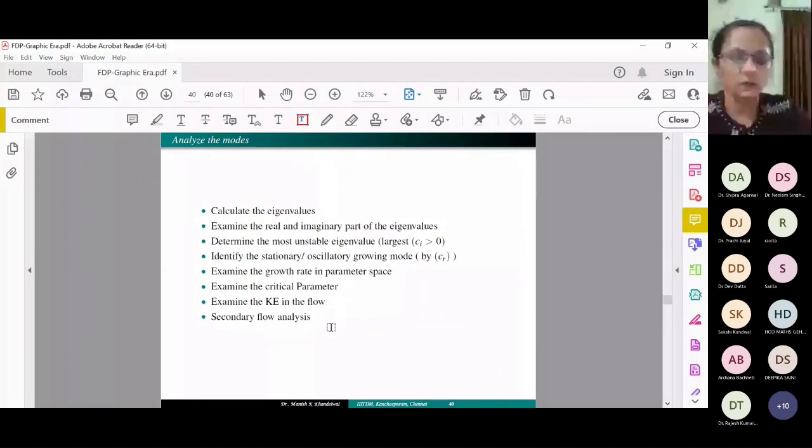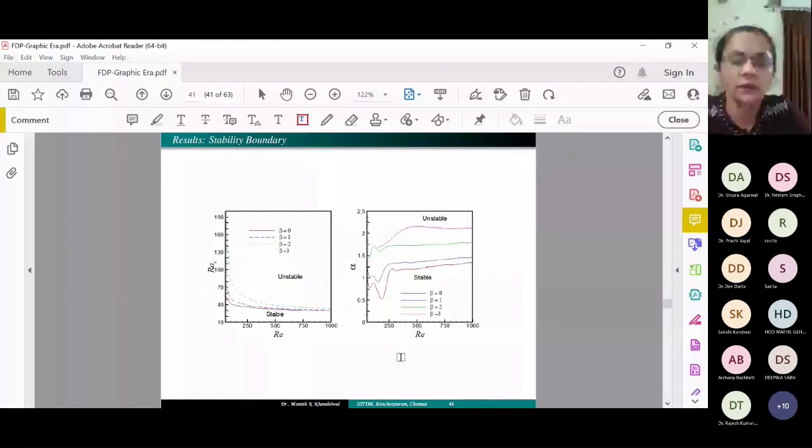Here I have shown it graphically. Once we calculate the critical point, after the critical point we declare the unstable situation, and beyond it the stable situation. We do not say straightforwardly that it is stable; we say that the flow is linearly stable. Below that point it may be unstable, but beyond this line, whatever analysis you implement, the flow is always going to be unstable. So according to the wave number, with respect to the Reynolds number and the Rayleigh number, we develop this type of boundary.